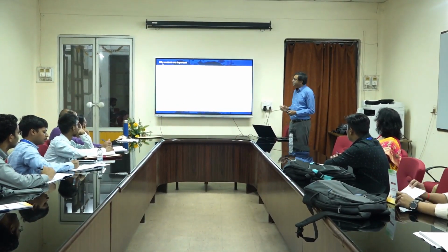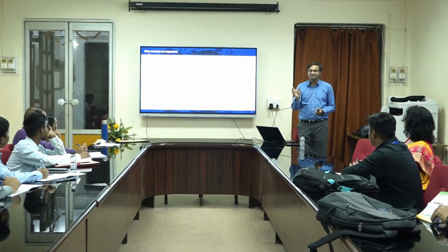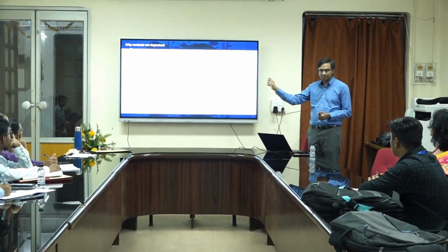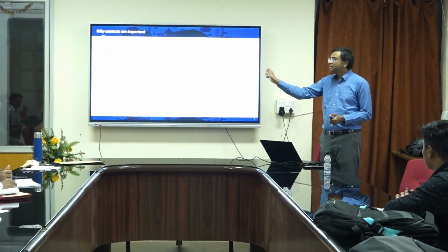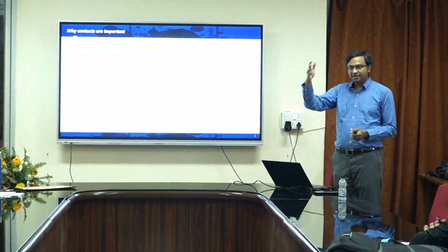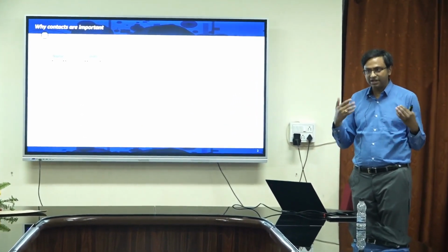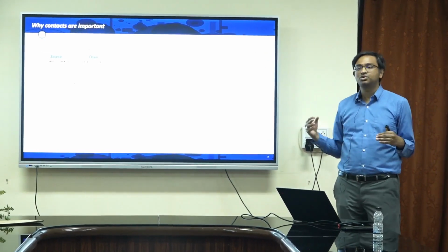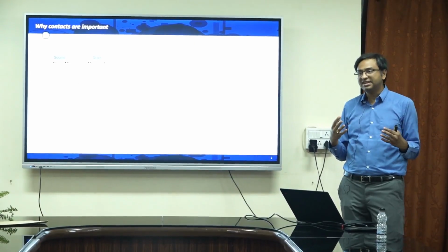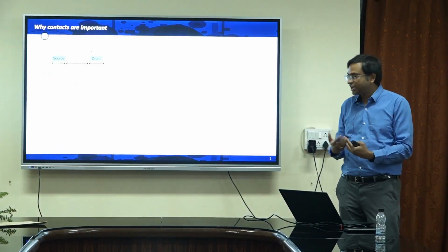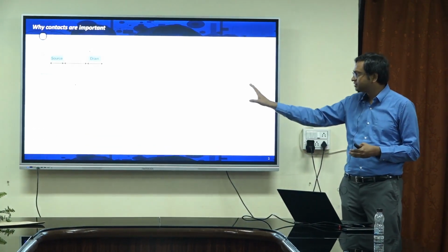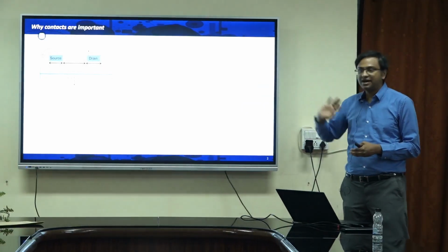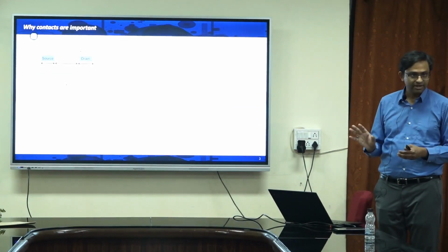So now when you have a structure like this, there are generally three resistances. Okay, one is the resistance of the channel, and the other are the resistances at this metal 2D interface, because the electrons or the holes have to come from the drain or the source and get into the 2D material, and there they will face some resistance. Okay, and that is the contact resistance. So this is denoted by RC, and RCH is your channel resistance.